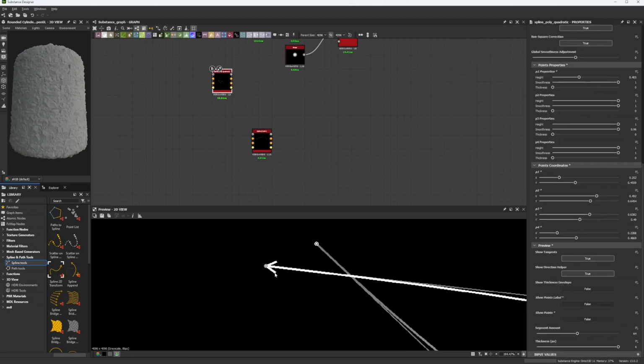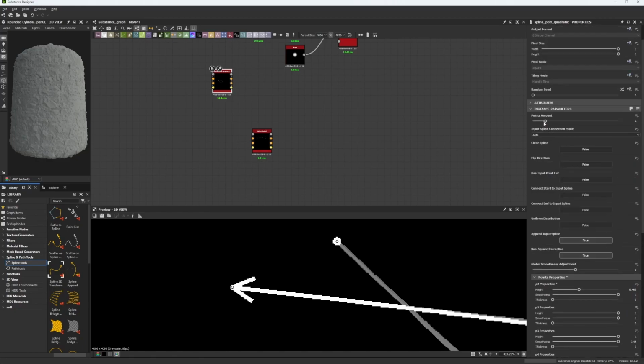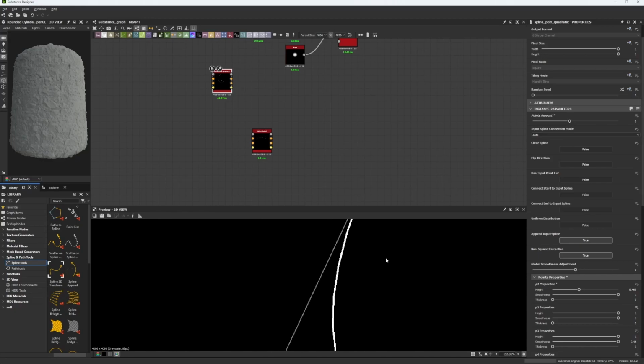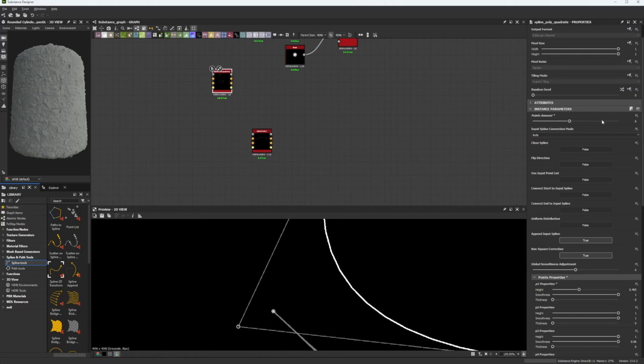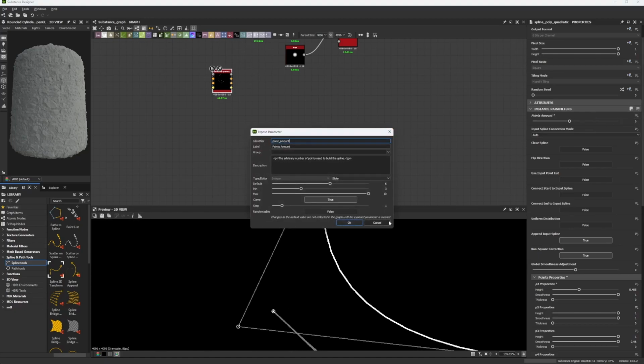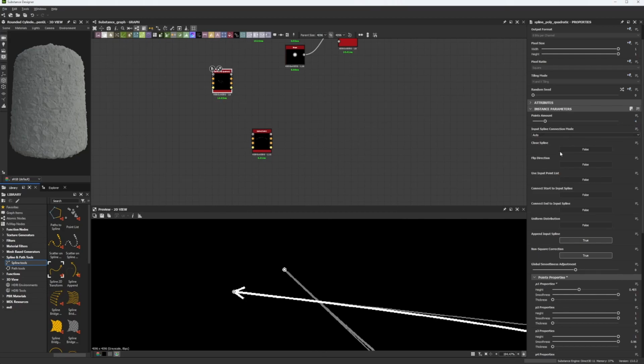So you see, every spline is going to have a starting point and an end point. The starting point is the one that only has a dot, while the end point has an arrow. That end point and that arrow show the direction everything's going. If I'm not mistaken, if I add a point, it's going to extend our line from the arrow, and the arrow extended to the other part. So we can turn this back to 4. You're going to leave it there.